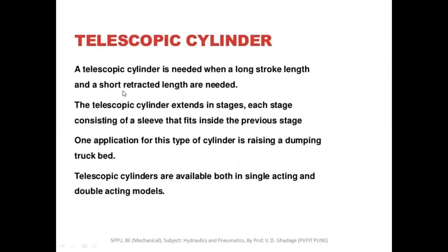Telescopic cylinder. A telescopic cylinder is needed when a long stroke length and short retracted length are needed. The telescopic cylinder extends in stages, each stage consisting of a sleeve that fits inside the previous stage.